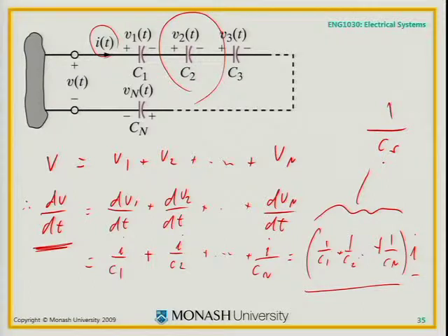How do you prove it? Well, you use what you know about it. Here we use Kirchhoff's voltage law with I equals C dV by dt, the fundamental VI relationship for a capacitor. So you could correspondingly prove that parallel capacitors must add up.